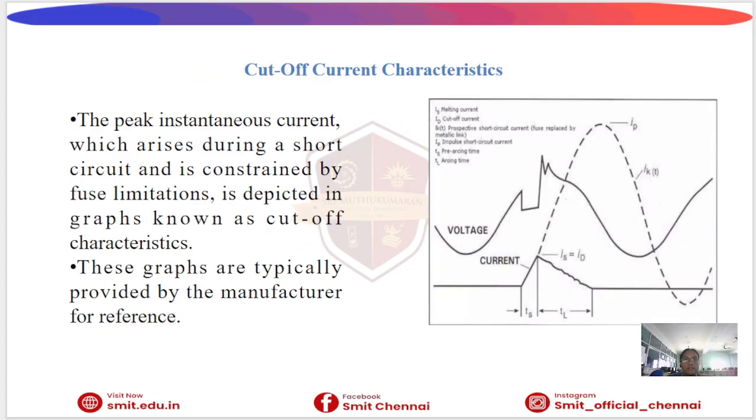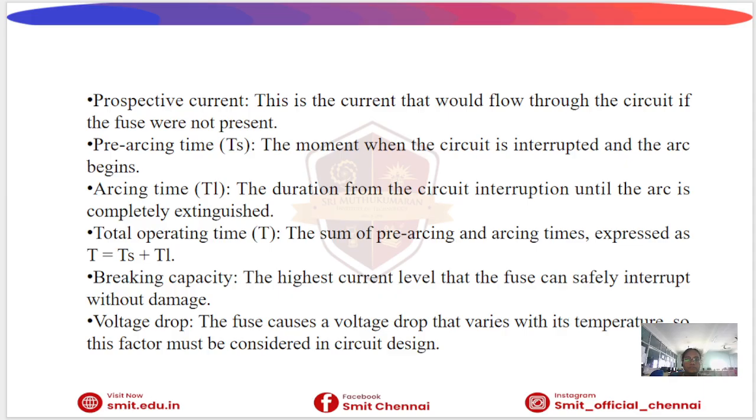Cutoff current characteristics. Cutoff current characteristics explain how the fuse interrupts current during a fault. Important terms include prospective current, pre-arcing time, arcing time, total operating time, and breaking capacity. Prospective current: the current that would flow if the fuse was not present.